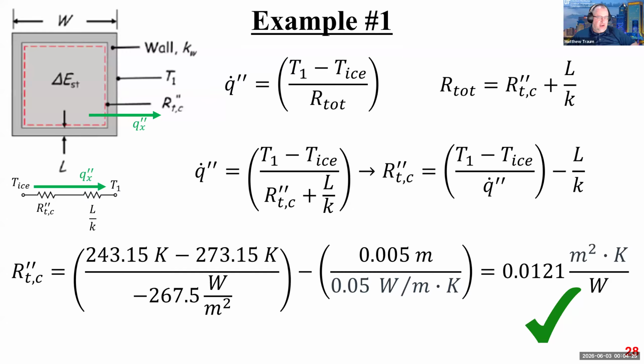and then plus the resistance to heat transfer presented by the wall, right? So you can actually see it here. Here's my thermal circuit. Here's T ice, the temperature of the ice. Here's the heat flux. And here's T of the outer wall, which I set at 30 Celsius, minus 30 Celsius. Here's the resistance associated with the ice interface. Here is the resistance associated with the wall. They are resistances in series. They get added up. So they're added up here to give me R total.